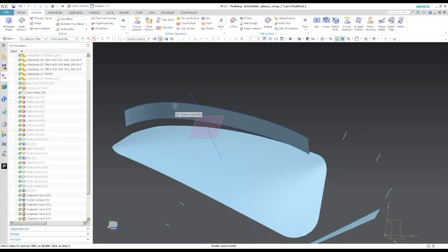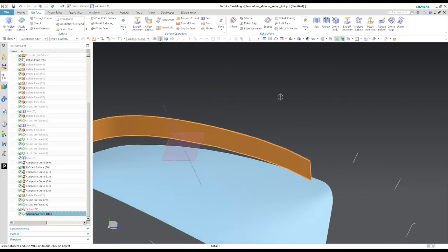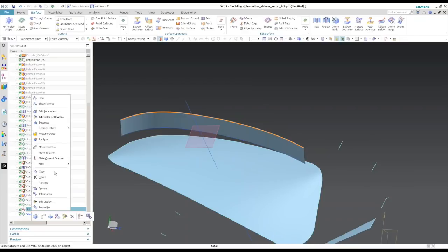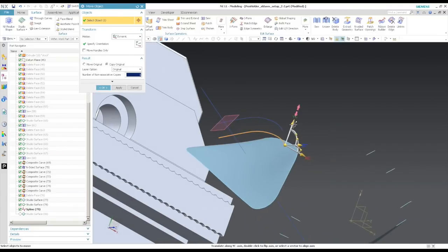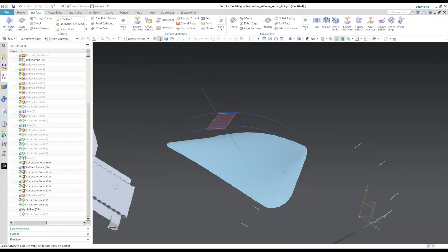It allows you to use your surfaces to control the tool axis. So if you have something with crazy face normals, you can smooth that out with this reference surface that not only will project the toolpath, but you can use it as a drive geometry for the normals for your toolpath. So to show that, let me roll back here to give you an idea what that looks like. Let's pull this further down, hide the other one.